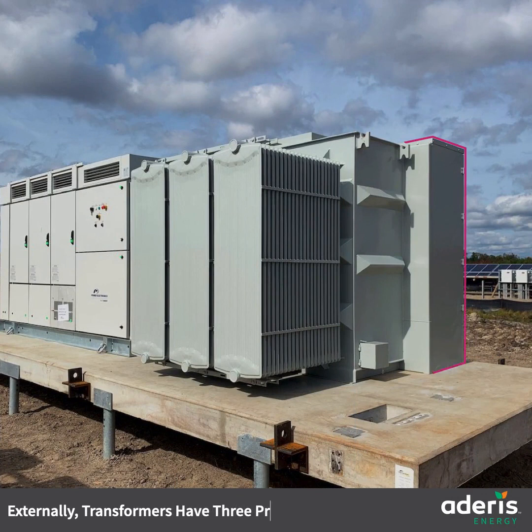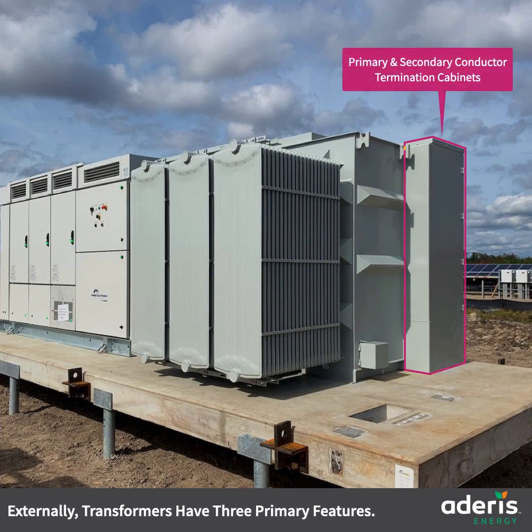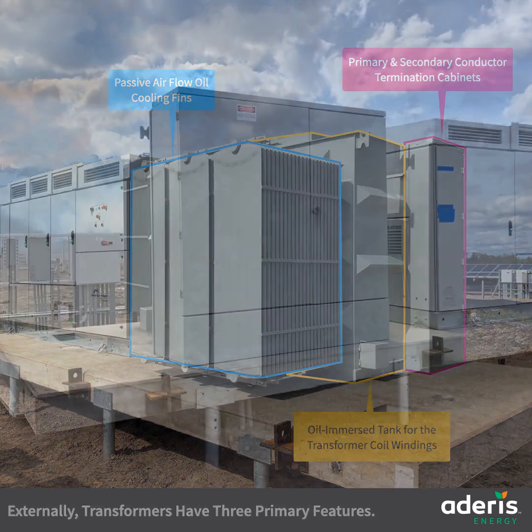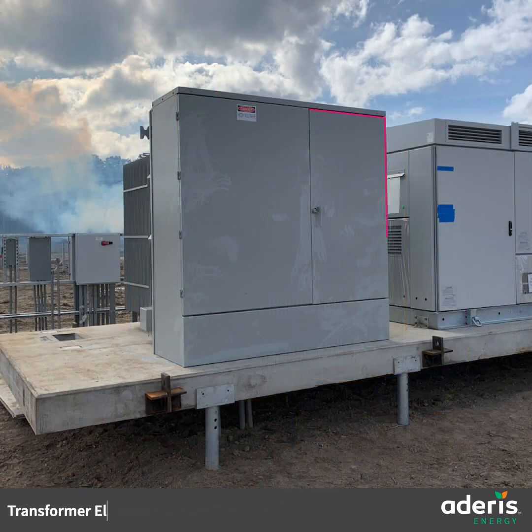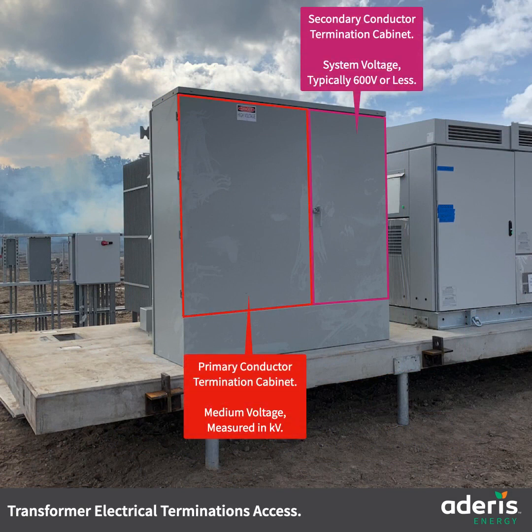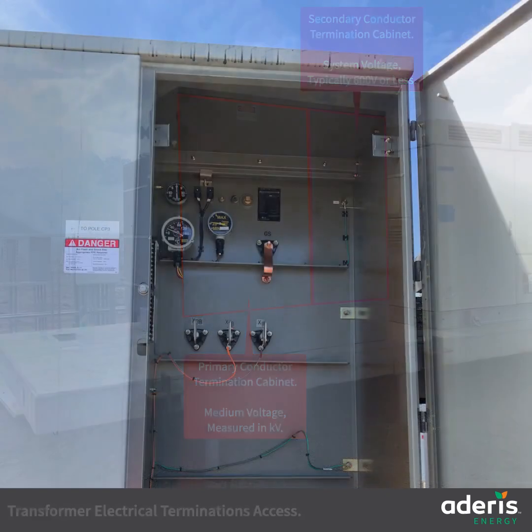Externally, transformers have three primary features: the primary and secondary conductor termination cabinets, the oil-immersed tank for the transformer coil windings, and the passive airflow oil cooling fins. Transformer electrical terminations access. The secondary conductor termination cabinet has a system voltage of typically 600 volts or less, while the primary conductor termination cabinet has a medium voltage measured in kilovolts.